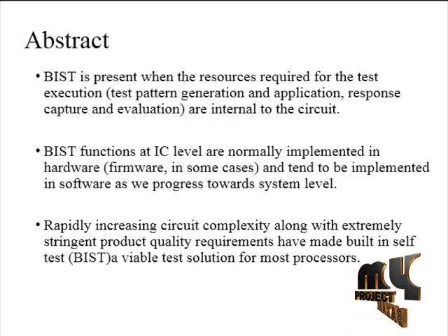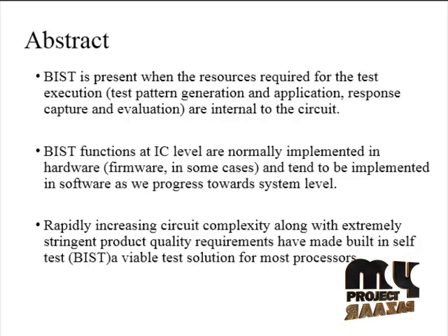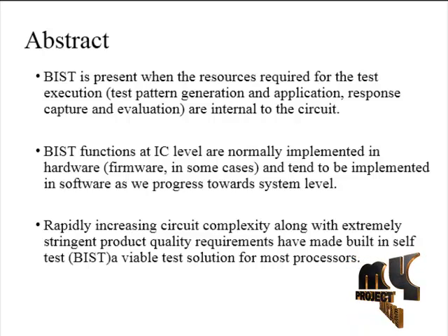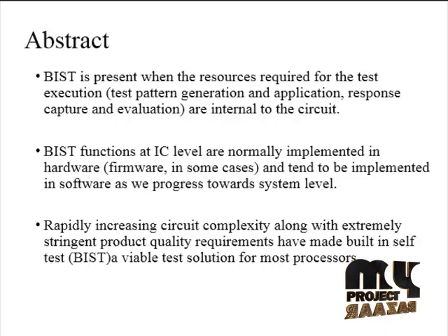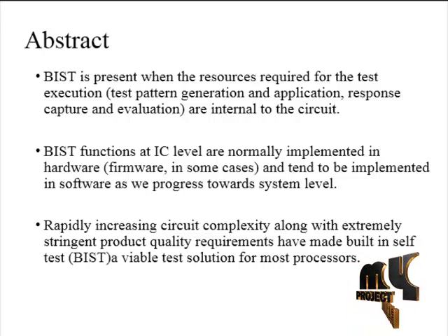Shrinking process technology and faster memory bus data continue to drive complexity in the input-output design. The surge in complexity brings with it increased design bugs. While some of these bugs, such as logic bugs, can be detected at the pre-silicon stage, others, such as cross-coupling of adjacent data lanes, voltage droop, ground bounce, power bounce, timing error due to process shifts, etc., remain undetected.